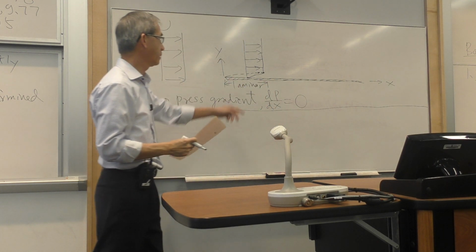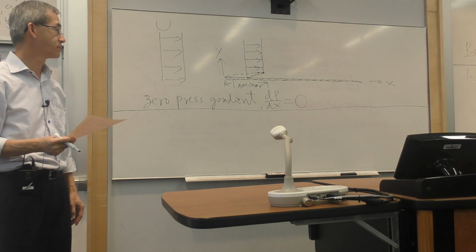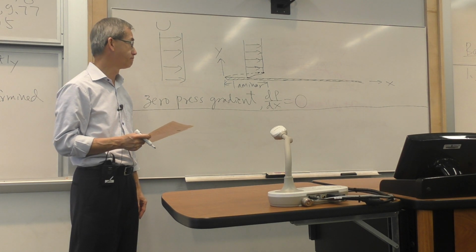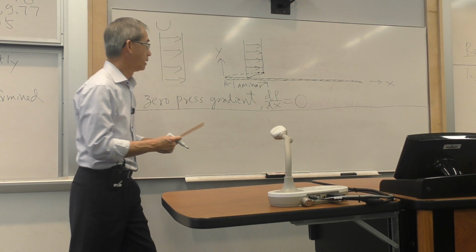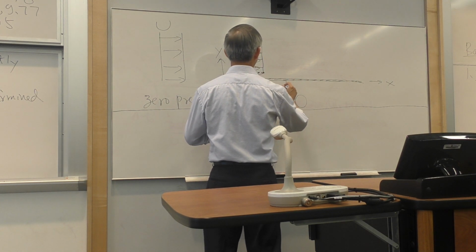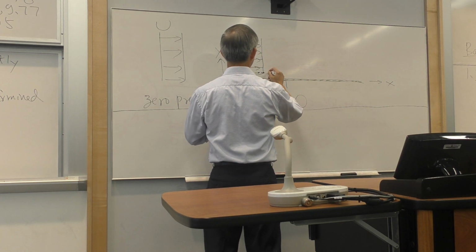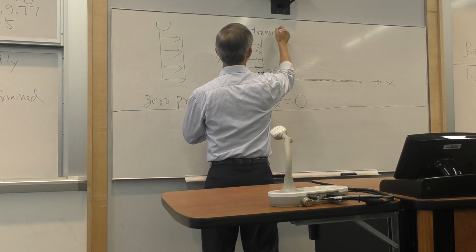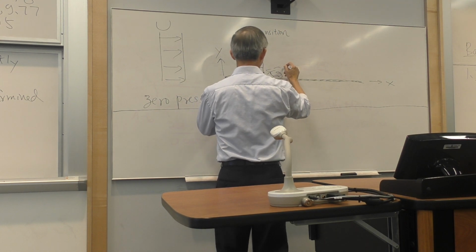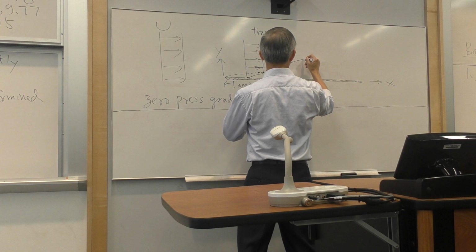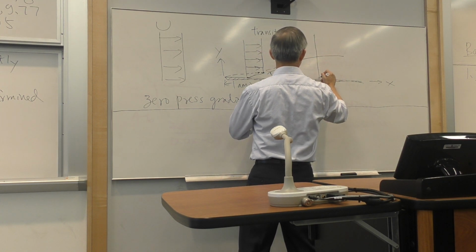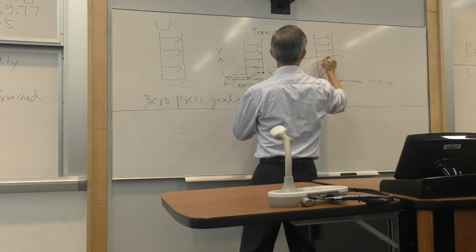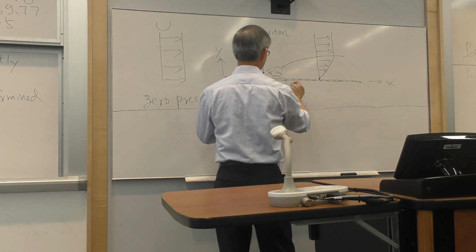The characteristic of that layer, which we'll call the boundary layer, from the leading edge on, is laminar to start with, and then you will go through a transition region, and I use some wiggle here to designate the transition region, beyond which the flow of the boundary layer will become turbulent.